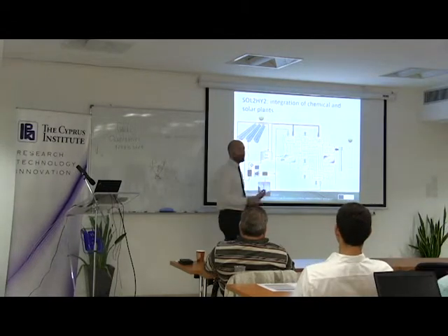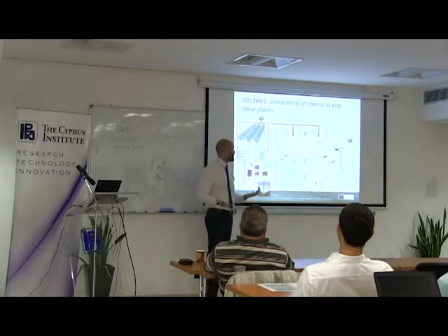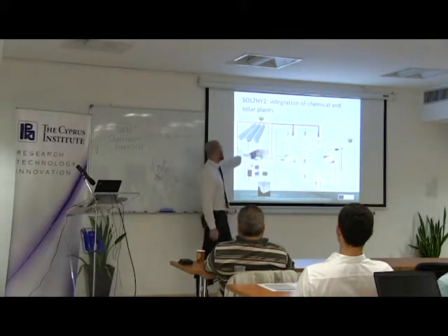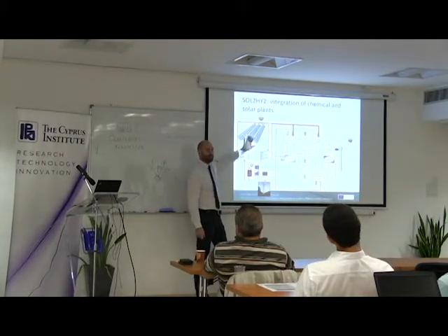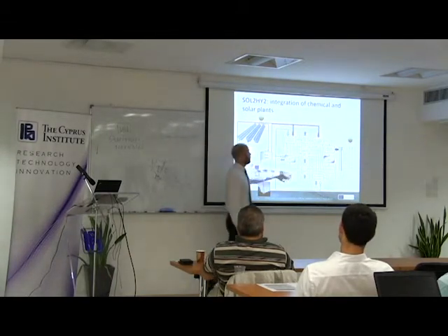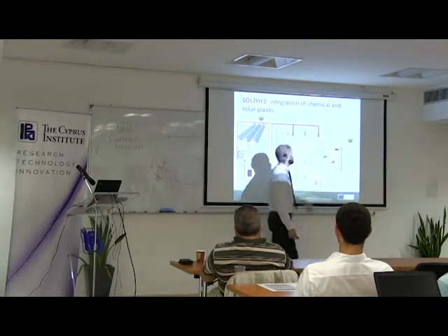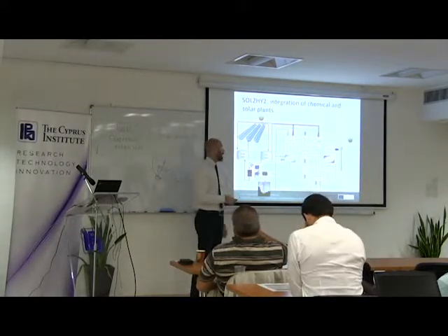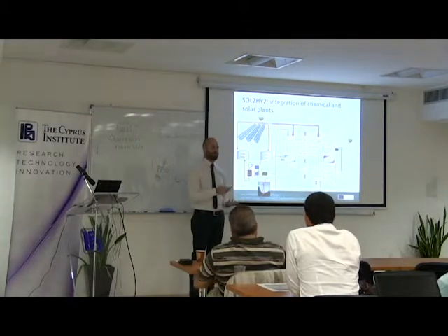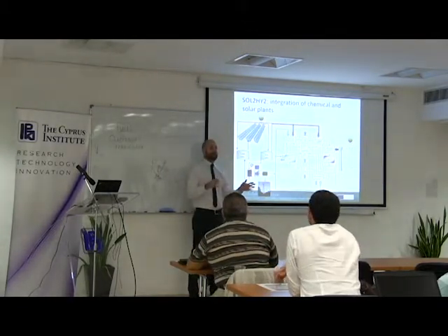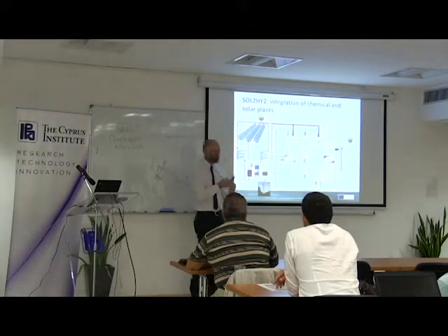So, according to what we have set up to today, we can provide this medium temperature heat by using a parabolic trough system, which can also rely on storage. For the high temperature step, we don't have a choice, we must go for a point focusing system. And unfortunately, we don't have a consolidated storage technology here to ensure the same duration of storage.